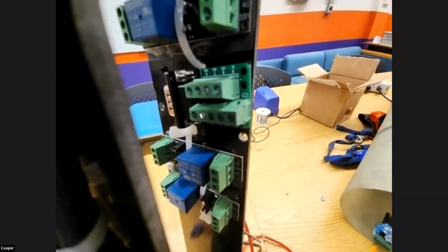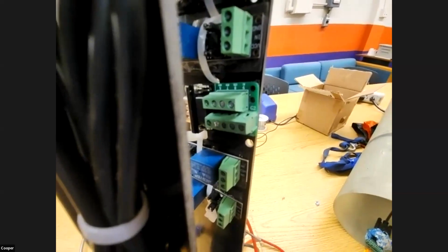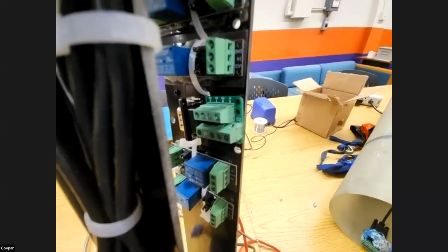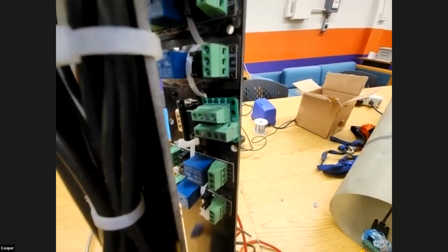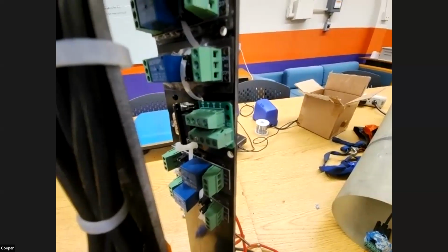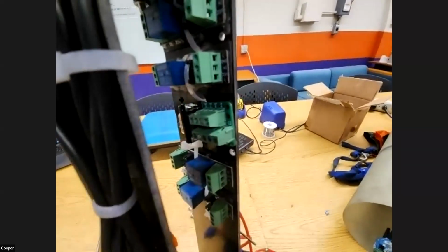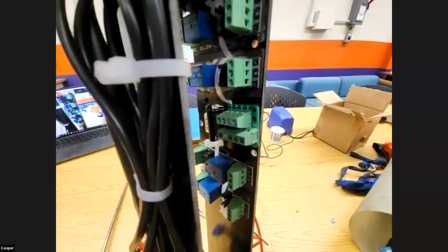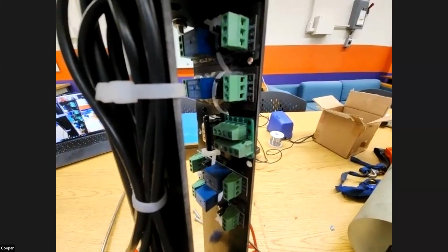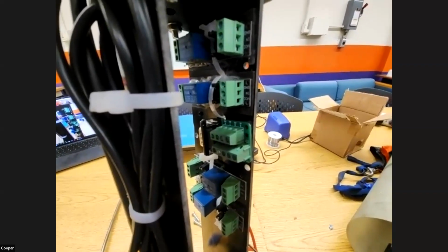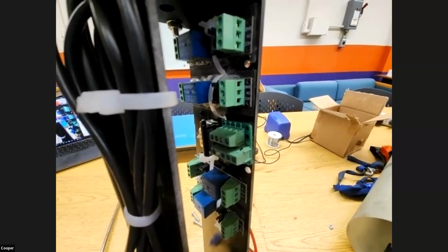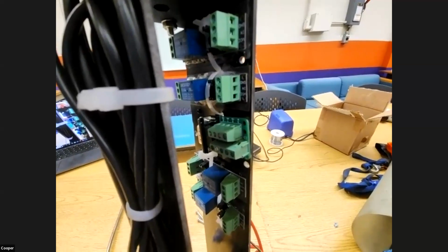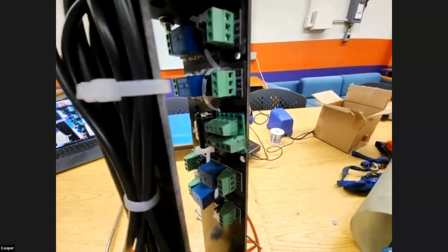Okay, I guess the key piece that I'm worried about is with all the SRAD stuff that you have thrown around there, because I'm seeing MOSFETs and all sorts of interconnections. I'm totally okay with that, but I want to make sure that we're not building some type of advanced capability into the standard Stratologger CF function. No, the Stratologger gets power, it gets all of its enables correct, and then its lines run straight to the parachutes with nothing in between, except for the connector, obviously.